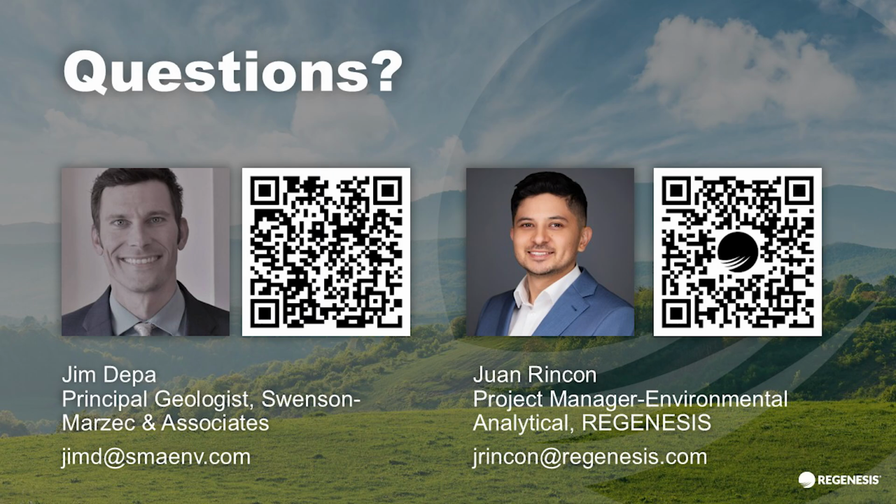Okay, thanks, Juan. So here's a question for Jim. Jim, the question here is, can injection plans be made to treat groundwater plumes? Yes, and I've created a few of those, specifically for PFAS, building a sort of an interception wall for plumes. I would caution against doing this with just monitoring well data. However, that can be done, especially if there are a lot of monitoring wells.